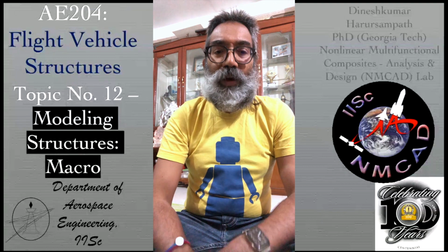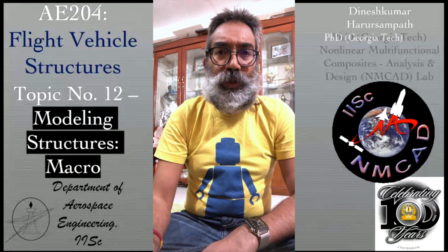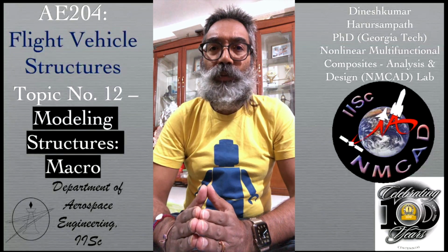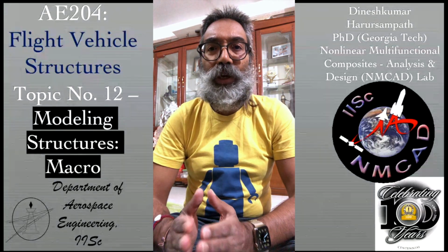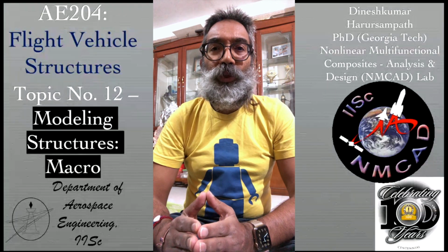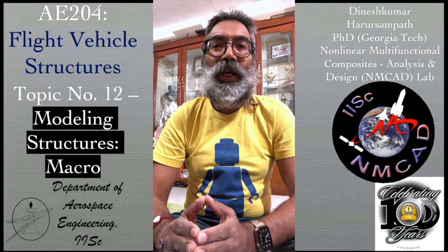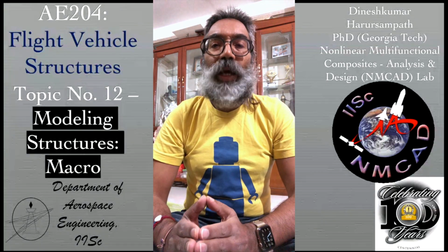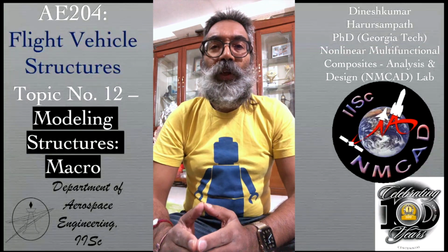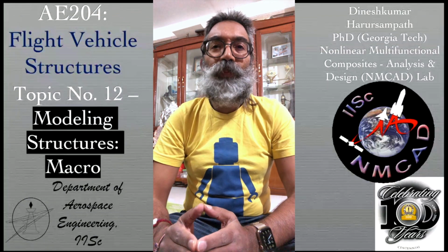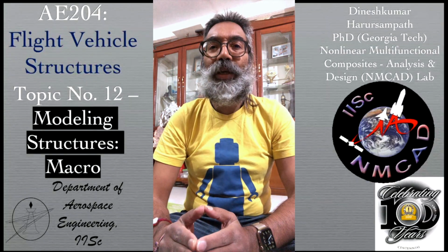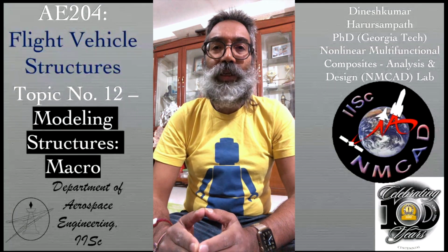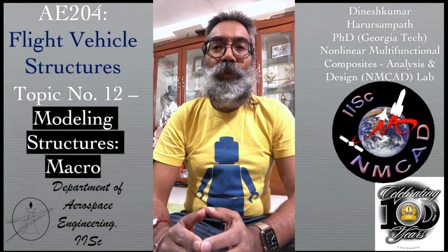But now that we have learned these basic aspects, that is in terms of Y fiber, Y matrix, Y composite, now we are in a position to put them together, because in the micromechanics we also learned of this concept of the volume fraction. So based on that volume fraction, now we know how, given the properties of the fiber and the matrix, we can calculate the properties of the overall composite. So that property we are now able to determine.